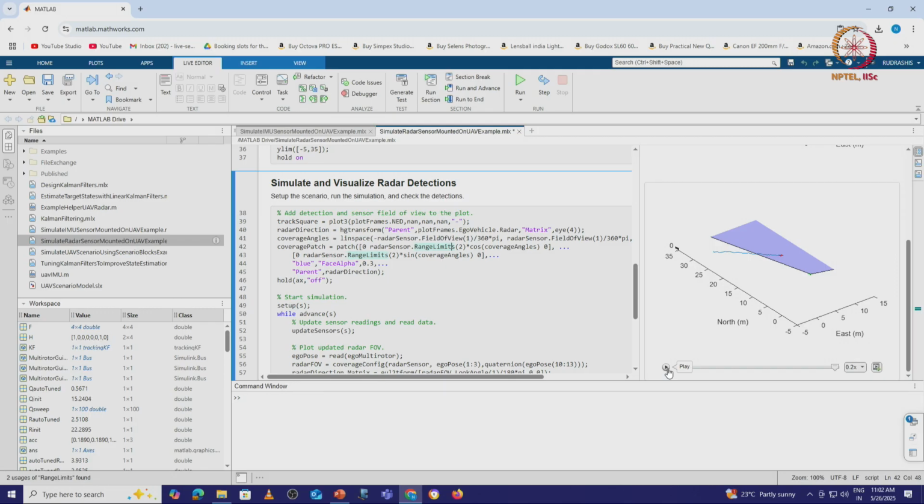Once we have a 6 degree of freedom model, once we create scenarios, like for example, if you are looking at obstacle avoidance, you need to create a scenario where obstacles could be present. Then we understand the control, we talk about speed control or attitude control system, or if you are talking about precision landing, we need to talk about height control system. Once we have this and navigation lecture is done, we will look at how we can integrate all of this to simulate the complete system, and we look at the real world data and what we measure in a simulated world.